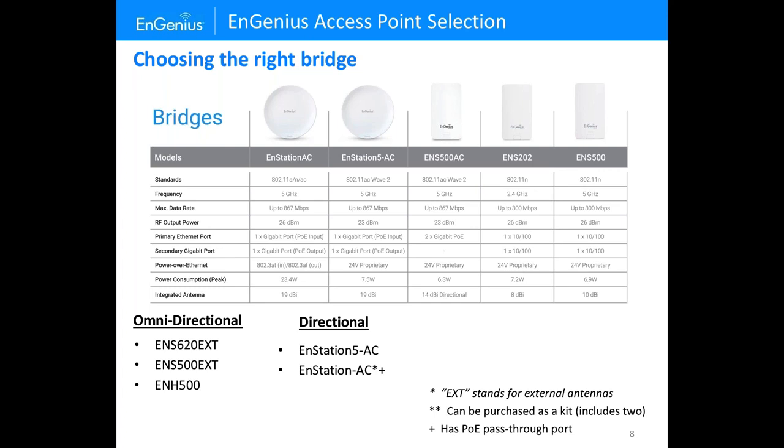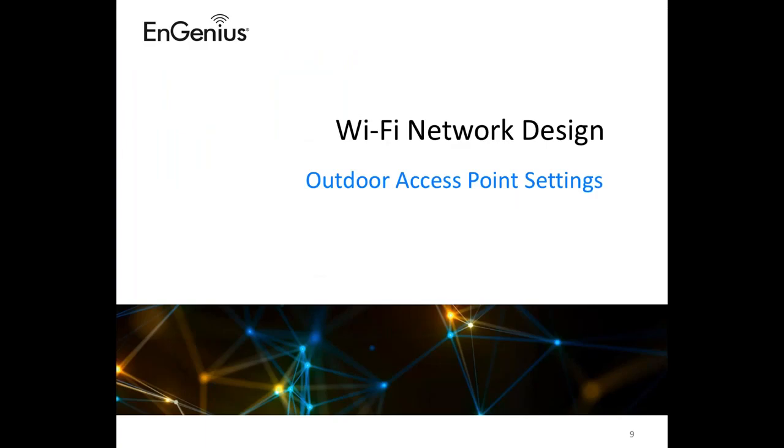You could do bridging, although we don't recommend it. This is a best practice webinar, and we don't recommend doing bridging on 2.4 gigahertz. Yes, 2.4 technically propagates better or further, but when you're bridging, you could make up for that and more with antenna gain, and also a smaller Fresnel zone, which we'll talk about, because of 5 gigahertz. So you actually wind up having better bridging with 5 gigahertz.